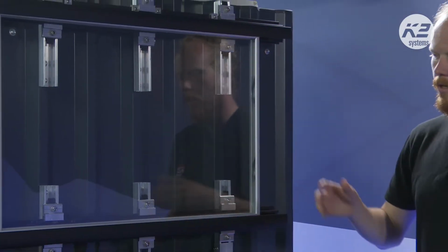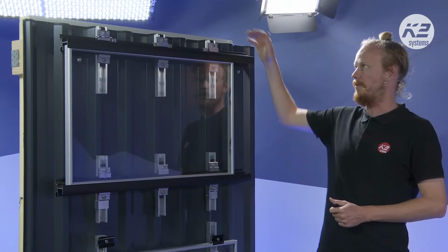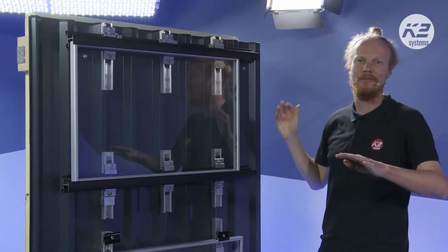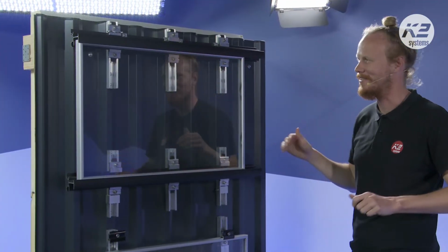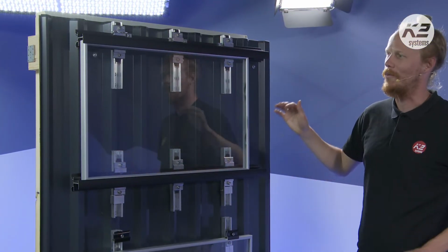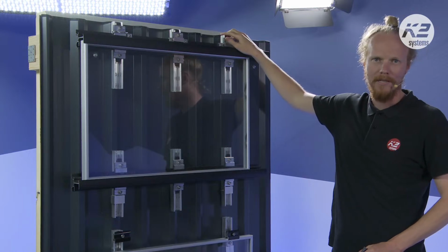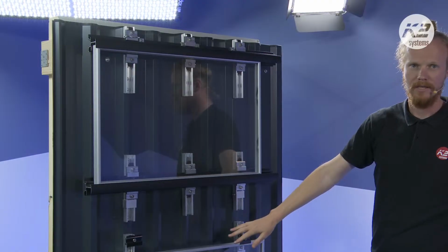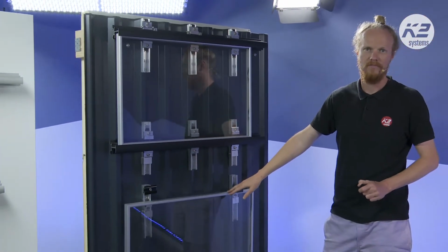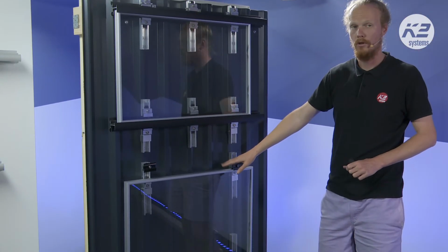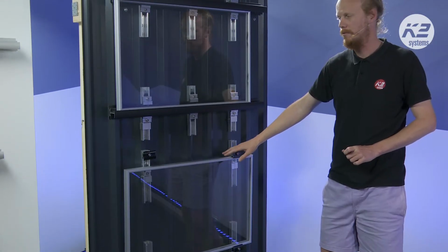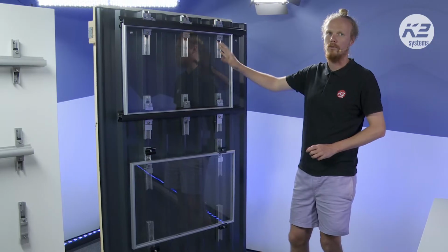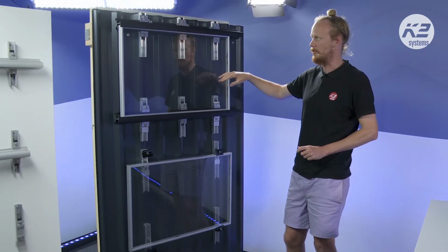So with the MultiRail, which we have here for the trapezoidal roofing or sheeting, sorry, and I apologize again for using roofing all the time. It's what we're usually talking about. So for the facades and the wall, the MultiRail is the option where we can do the insertion rail and the facade clamps. Facade clamps only in landscape, horizontal, but with the insertion rail, we can do portrait or landscape, vertical or horizontal.